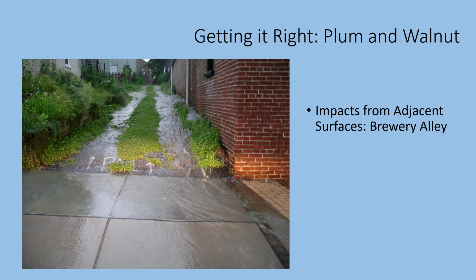So after our first pilot project lesson learned and retrofit, we also wanted to take a look at what other items might be impacting the performance of this system. And we didn't have to look very far. There was a private alley that actually ran adjacent to the brewing company that you can see pictured here. It was unfinished, unpaved, and unmaintained. And when it would rain, it would bring a lot of gravel and sediment into that bioretention system that you saw on the previous slides. Next slide.